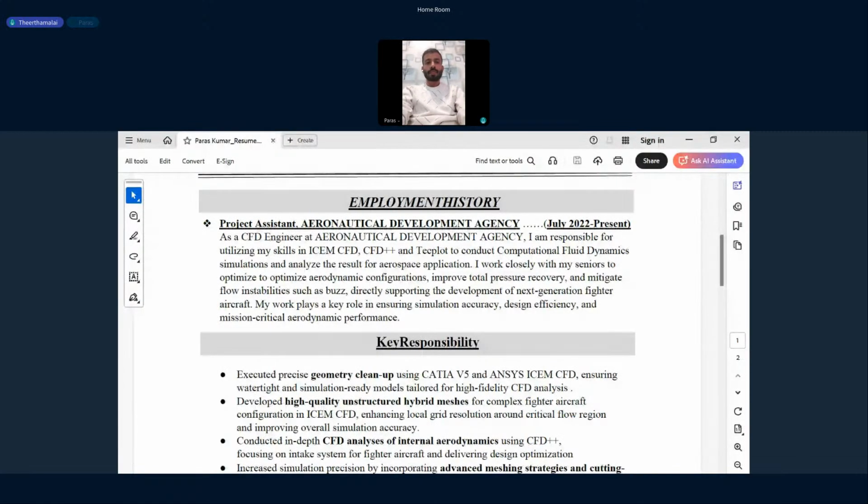So the canard, whichever is in the front, will aid the lift. So they want high maneuverability, that's why normally they use canard control. If you tilt the canard in the same direction, you will get the lift immediately. That's why high maneuverable missiles use canard control. Okay, understood now.